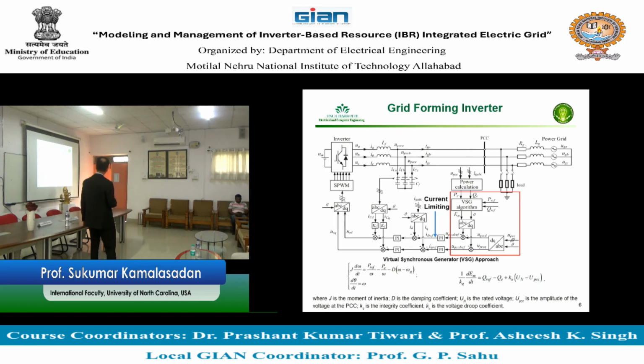So that reactive power emulation you can do as a concept here by looking at the voltage at the nominal value, the PCC value, and adding that to the reactive power reference. So this is a voltage and reactive power combination. And then utilizing a time constant, you say that as E. In the excitation model for a synchronous generator, there are different ways of excitation. You have a reactive power excitation, a voltage based excitation, and a reactive power and voltage combination excitation system. All those excitation models you can represent in here to generate the voltage.